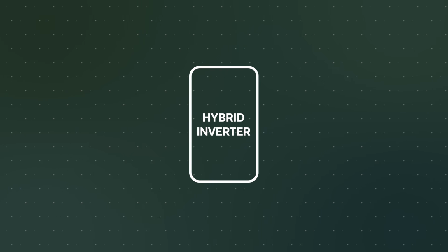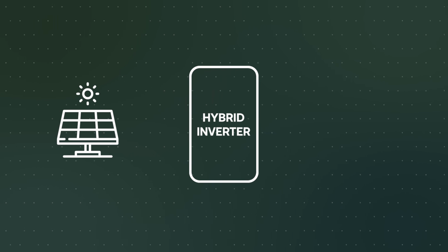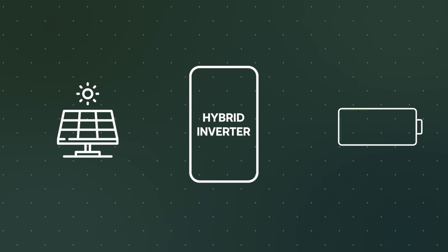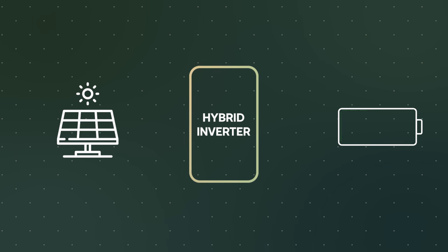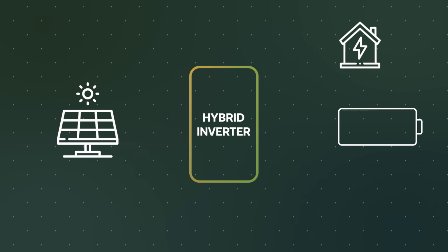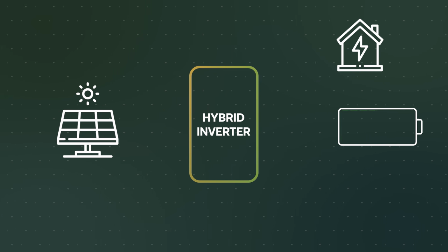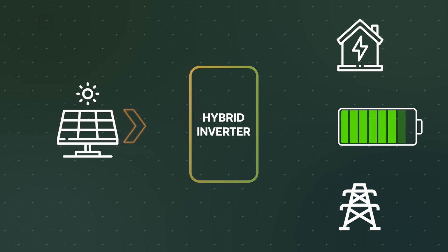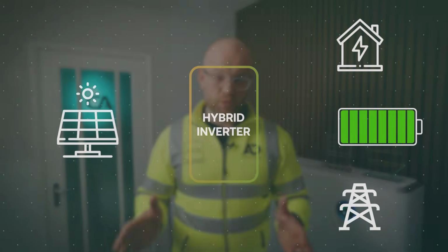That leads me quite nicely on to the next style of inverter, which is a hybrid inverter. What the hybrid basically indicates is that we can install battery storage into that inverter effectively. We don't need a separate one. It can do both functions, converting the DC to AC. It can monitor what you're doing inside your home. It can export to the grid, but it can also store that energy inside battery modules.